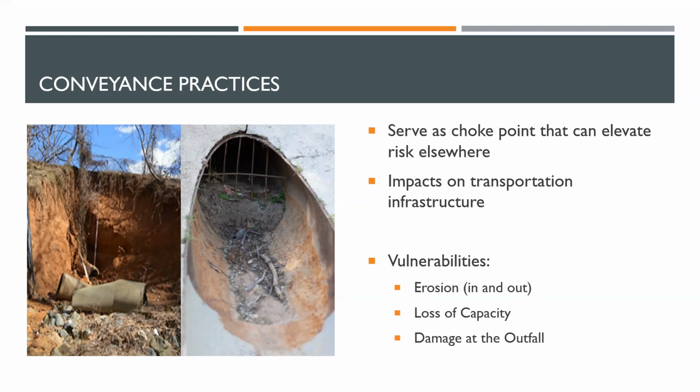So in some of our softer practices, maybe our swales and things like that, erosion can lead to an issue if they're designed to be non-erosive for the 10-year storm, but now that storm size is increasing, we might start to see some erosion in some of those practices, as well as in getting the water from the streets into and out of those systems, like at outfalls and things like that.